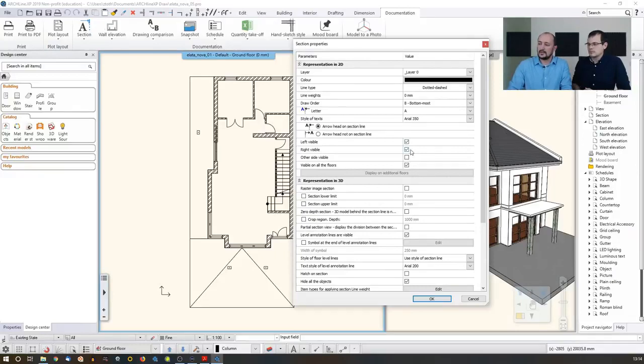For example, if I would like to see the symbols, like the two A symbols for the AA section, then I can enable that option. Let's talk about the partial section view, which we will enable now. It's useful if you have a long model. This model will also be part of a larger city location with a few grounds and surrounding buildings, and we would like to intersect only the building, and this is the option to do so. Right? So you won't intersect the whole world that you designed, but only that specific part, from the endpoint to the endpoint.